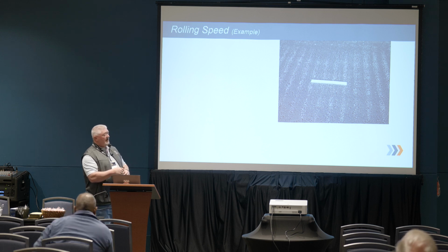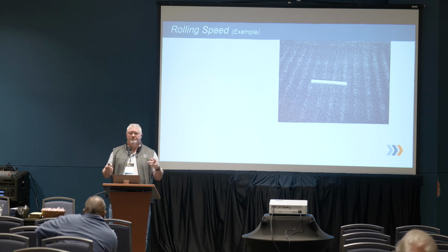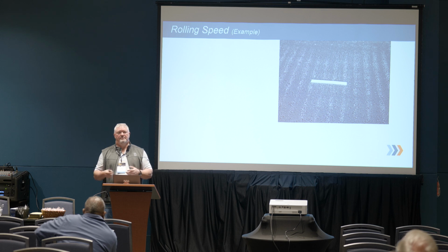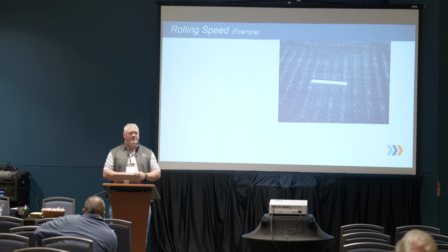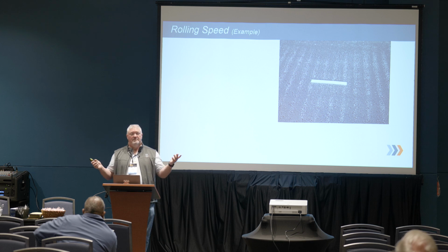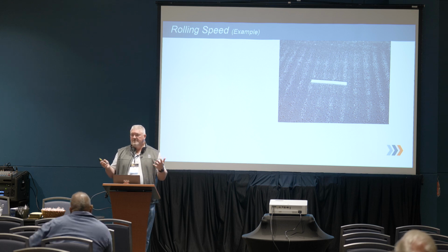So the paver was running 75 feet a minute, had 2 rollers, the 130 and a DD24. I stopped the roller operator, I said, how fast are you going? He said, I don't know. He said, I'm just trying to keep up to the paver. I said, well, what's your dial setting for your amplitude and your drums? He said, I don't know, the numbers are all out, we never change it anyway. I said, what's your frequency? He says, I don't know. He says, the button don't work. He says, it just runs.